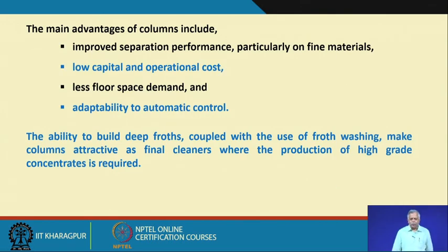The main advantages of columns include the improved separation performance, particularly on fine materials, because the residence time of the particle is much higher. The gap between your froth phase and your pulp phase is much higher in comparison to normal flotation cells, and they are very good for very fine materials, because fine materials have large surface area, so it is very difficult to maintain selectivity.